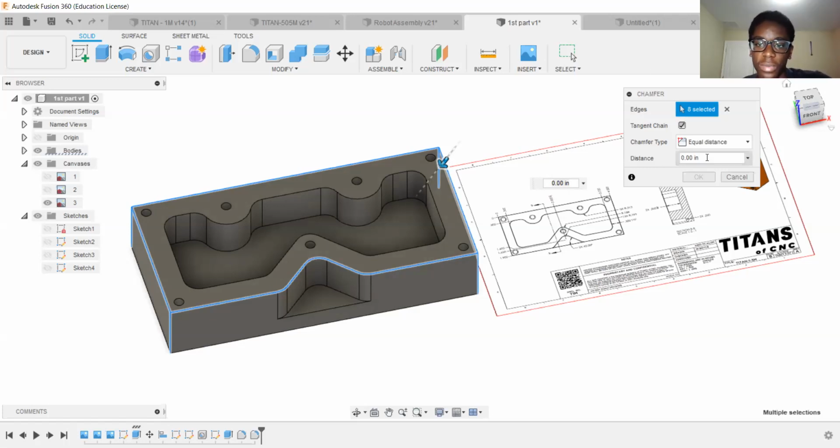Chamfers are easier to print too, right? Yeah, well, that's what I'm saying. The fillet is not going to, as the first few layers curve upwards, they're not going to print properly. Because it's going to be above the build plate, but extended out too far. If that makes sense. Whereas a chamfer is just a nice 45-degree angle. The printer will have no trouble with that.